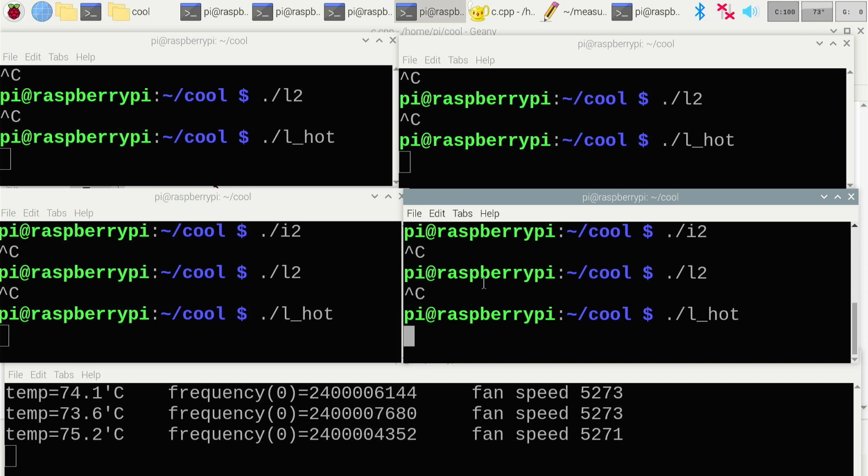You should use an energy meter as it makes it much quicker and easier to measure improvements to the program. It is important to me that you have to be careful when watching cooler tests. Some people measure the temperature far too rarely, and then it depends on chance whether the measurement was carried out at the moment when the CPU has reached 75 degrees Celsius, for example, or at the moment when the CPU was perhaps only 70 degrees Celsius hot.